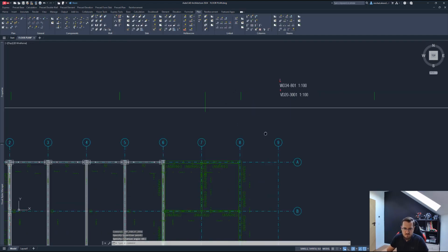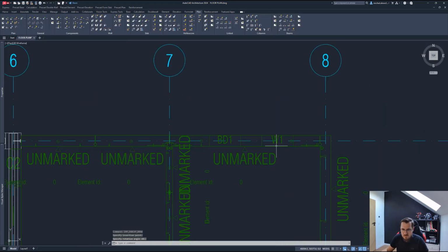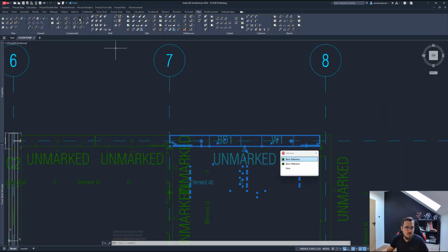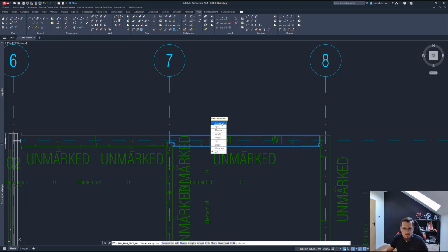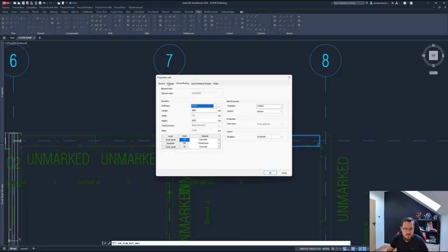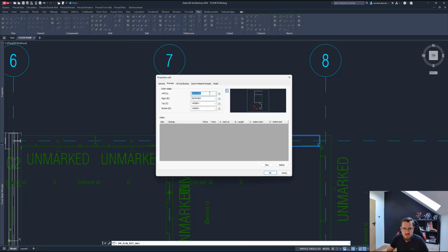Yep. Let me verify one thing. I'm going to edit the wall, go to properties and select the end caps and see what kind of end cap was applied. That's 804. Okay, so that's perfect. We can still do that. So this is this particular end cap. So I'll create this end cap as well for us,